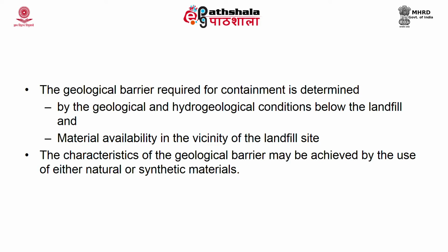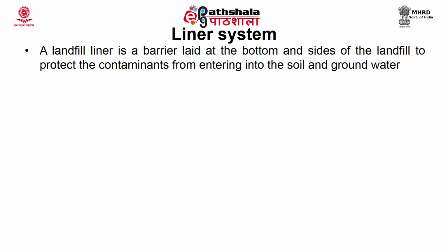That means you can design the geological barrier according to the nature of waste, using natural and synthetic materials. Natural materials can be clay or bentonite clay soil, and synthetic materials are polymers like PVC, high density polyethylene, low density polyethylene, etc.